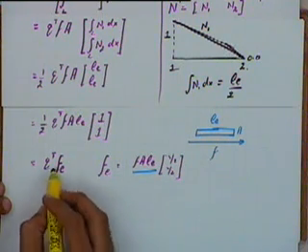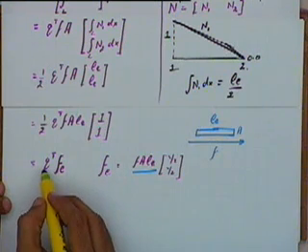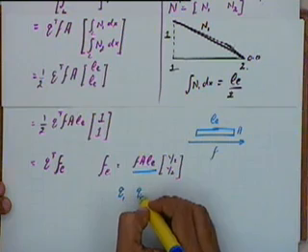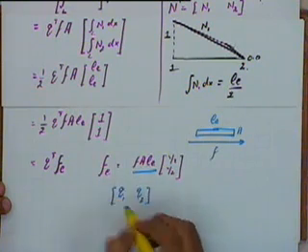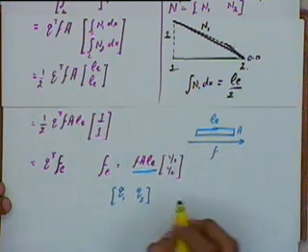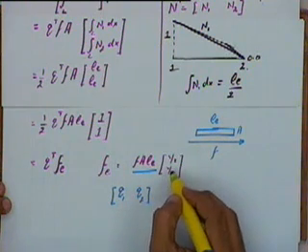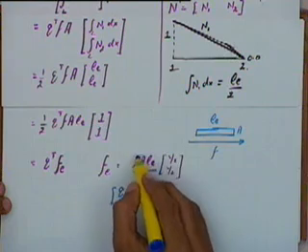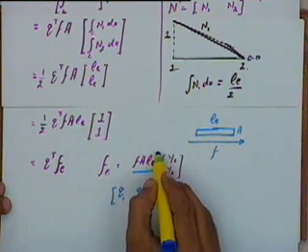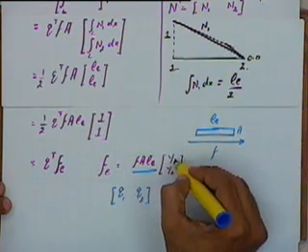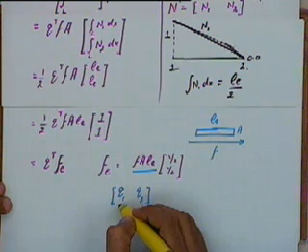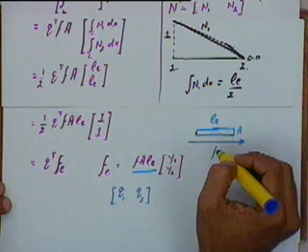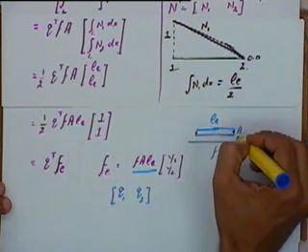And this Fe I am multiplying by Q transpose. Q transpose is nothing but Q1 Q2. So when I am multiplying Q1 Q2 by this, essentially what I am doing is whatever the total body force acting on that multiplied by half multiplied by Q1. Q1 is the deformation of this point, Q2 is the deformation of this point.